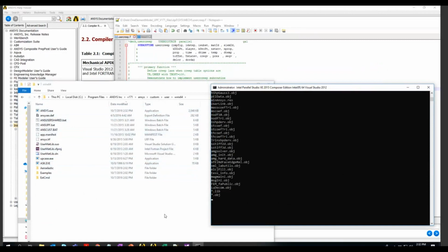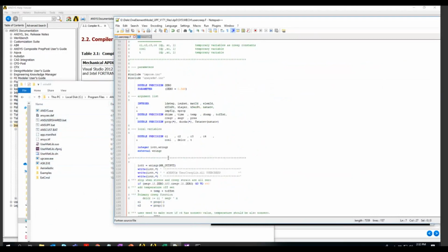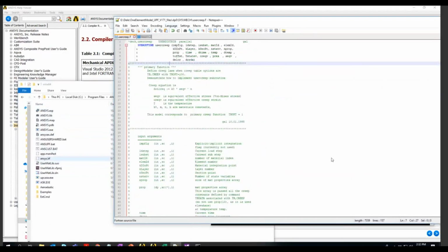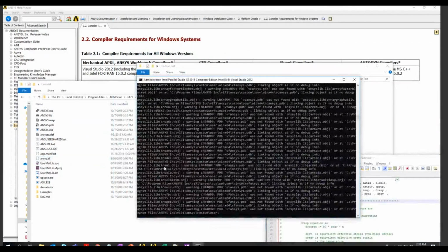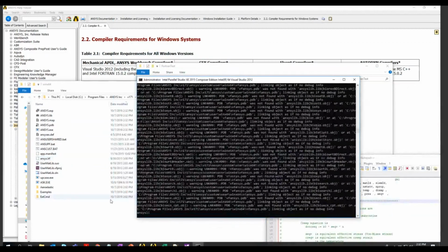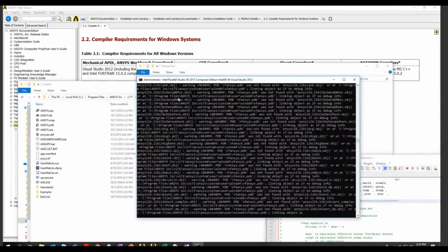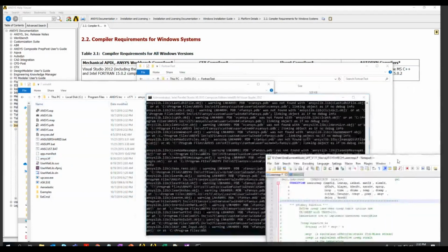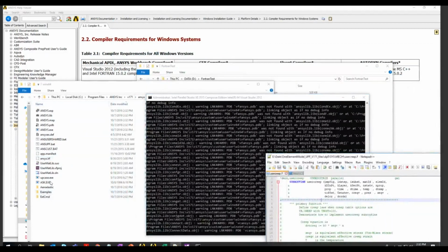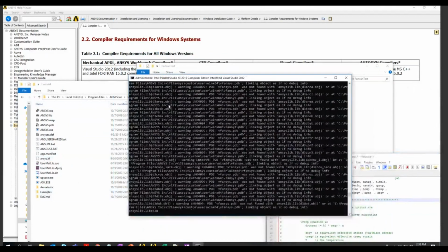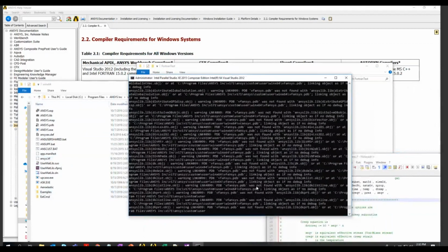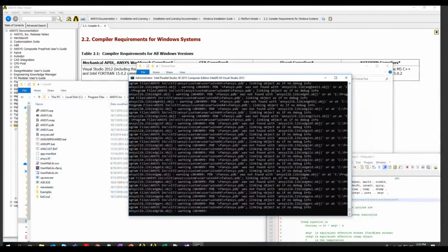Okay, this user creep file only computes the creep strain. There is an elastic strain, there is a plastic strain, and a whole lot of other calculations need to be done. Those calculations are done using the rest of the standard ANSYS subroutines. So whatever creep strain we compute needs to be linked with the rest. The first time, it is going to take some time to run this and link all the files. Let this run for some time.